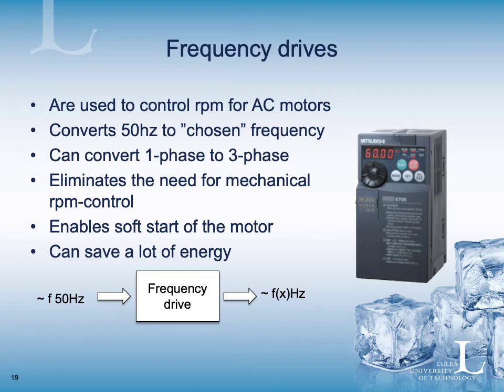So you feed it with 50 Hz, and then depending on what you want to do with the motor, you get an output frequency that is controlled by the frequency drive.